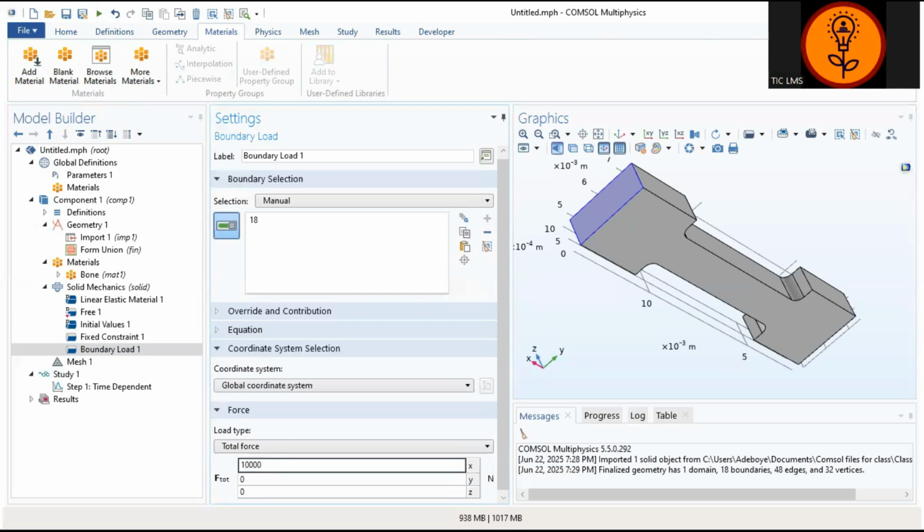and then we're going to put the units. Now, this is already in Newton, but we want it as 10,000 kilonewton. So put our square bracket open, then K is capital and N is capital, and then you close the square brackets. Now take note that when you make a mistake in these brackets, it may cause issues with computing. So you need to watch carefully.